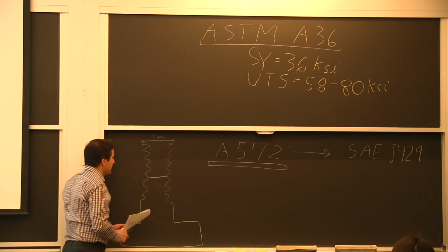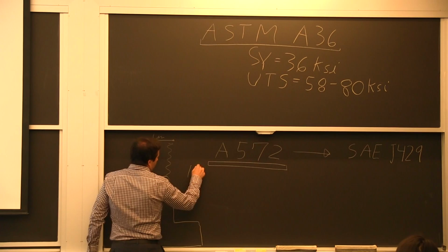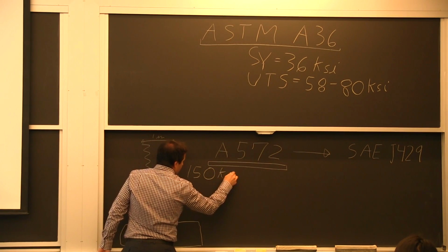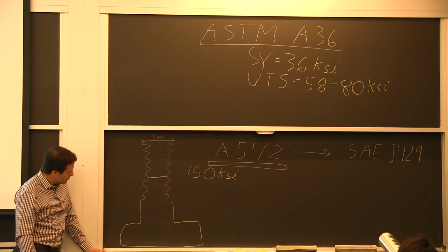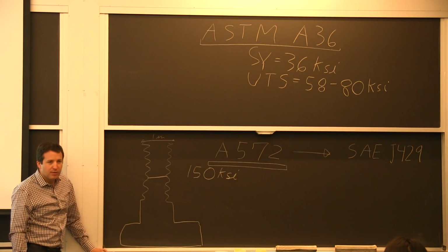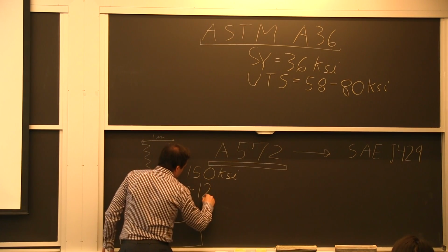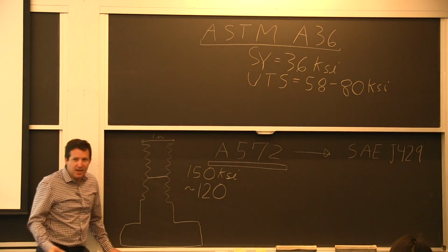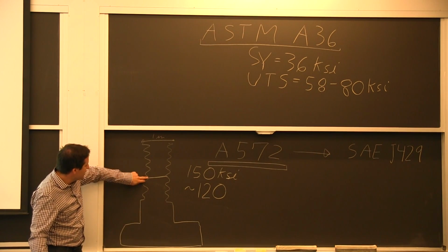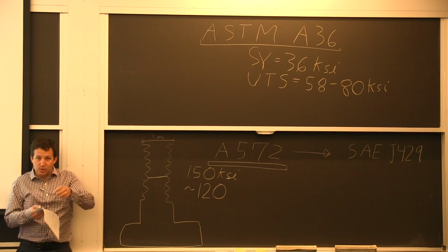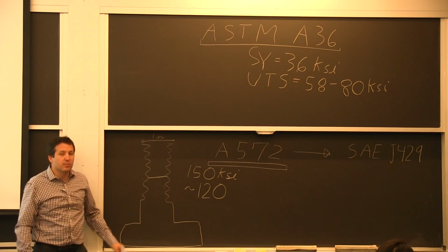But after that, say we're doing a grade 8 bolt, and it's telling us we have 150 KSI of tensile strength minimum. When you get to the net area here, it will be the equivalent, and I'm going to throw an approximate number here, of say 120, because it's net. Now, if I consider all the stress risers associated with a root like this, even if it's just pure tension going back and forth, I'm likely to have to knock this down by about a factor of 5.